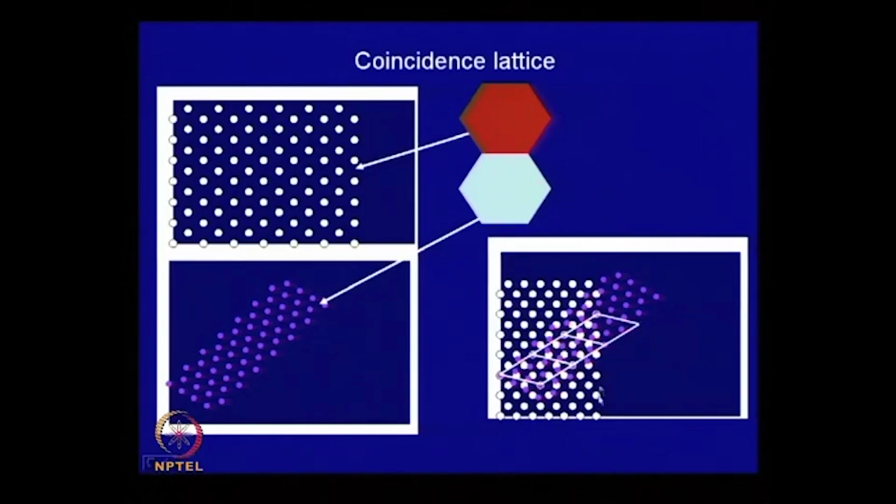The nature of the grain boundary people try to see based on the degree of rotation and the coincidence lattice type of relationship. It is not that these atoms are occupying this space, you just superimpose and see what are their coincident lattice sites. And what you can find out is that this coincident lattice distance is significantly larger than the atomic distance.